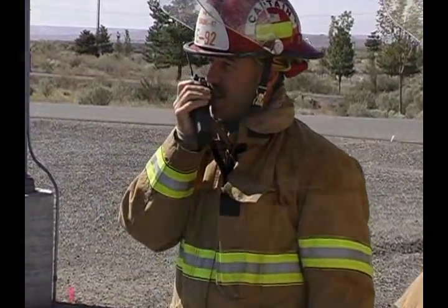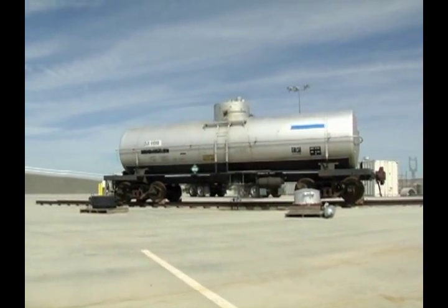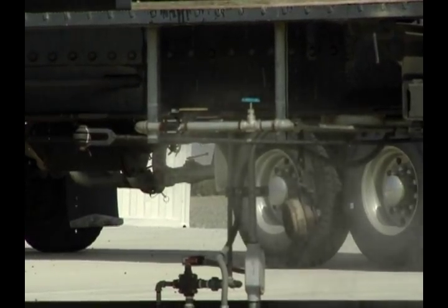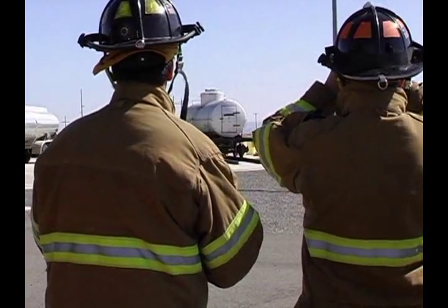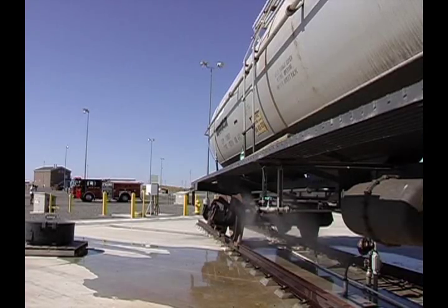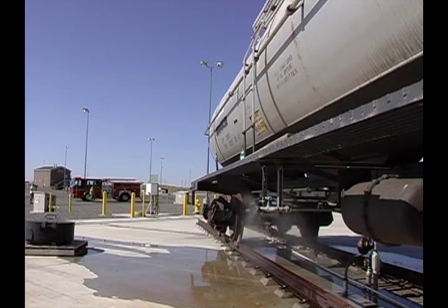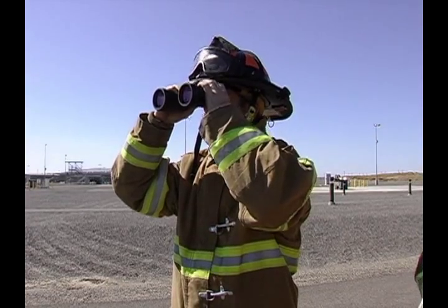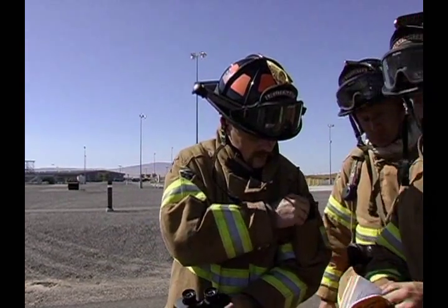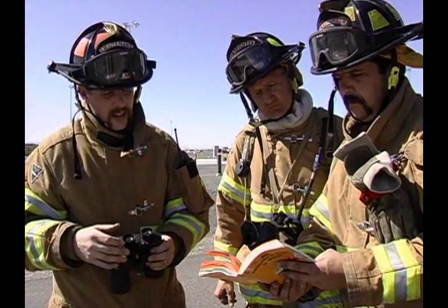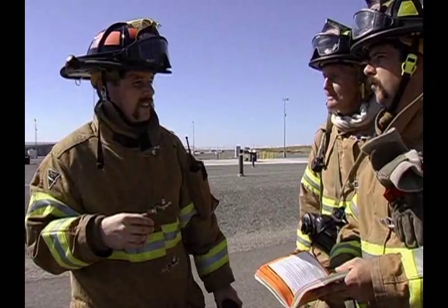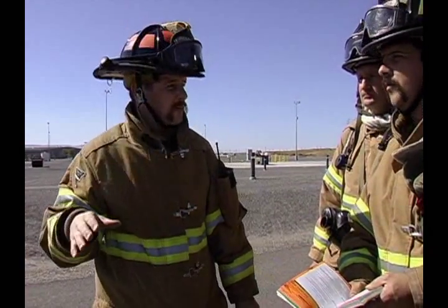And for Fire Engine 92 is on scene. In the case of a vapor release from a rail car, a select number of defensive options will best serve the needs of the incident. Vapor suppression or vapor dispersion will be your primary choices, as your objectives will be to knock the vapors down. This decision will influence how your team will proceed with the mitigation effort, the type of equipment you'll need for the job, and any plans for runoff containment.